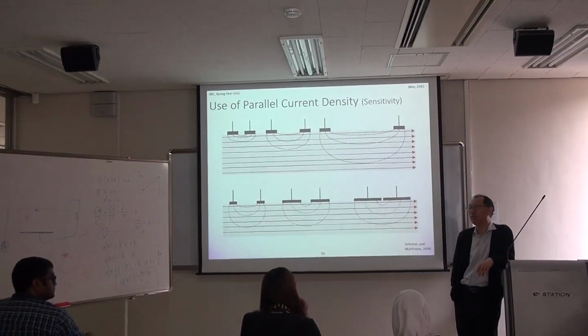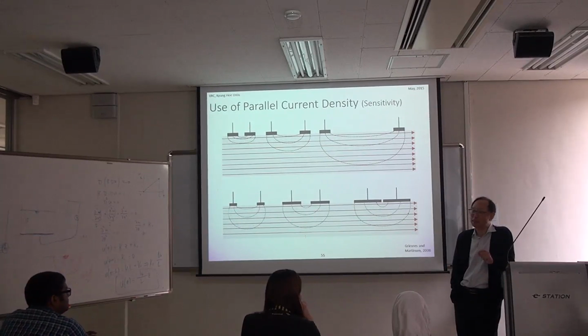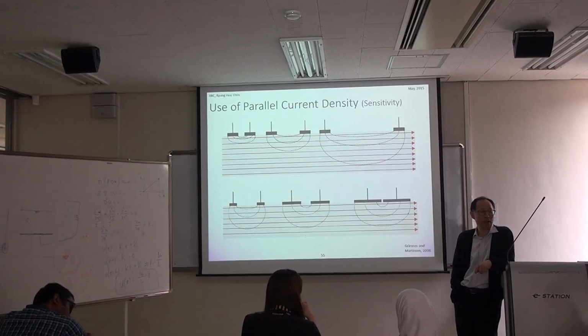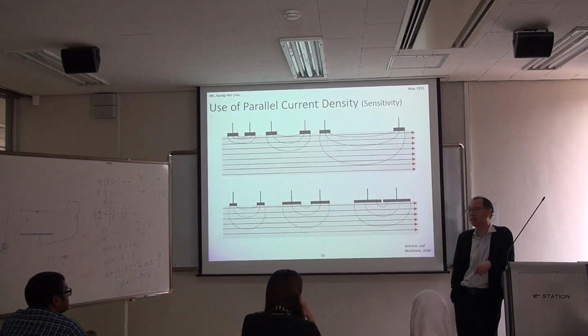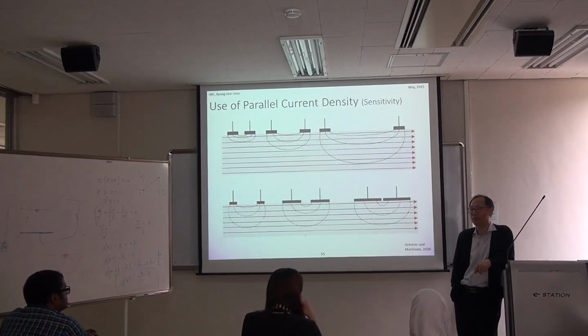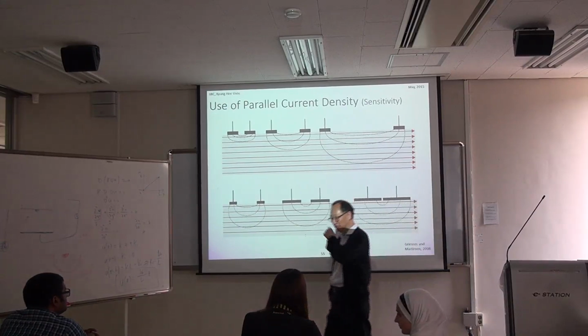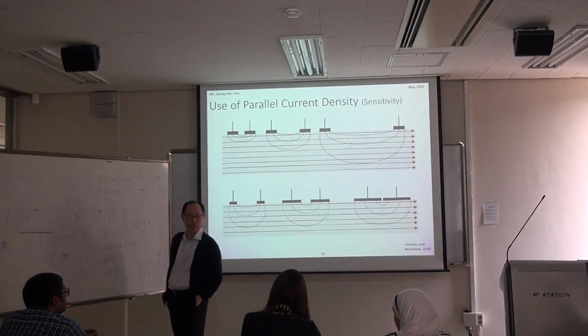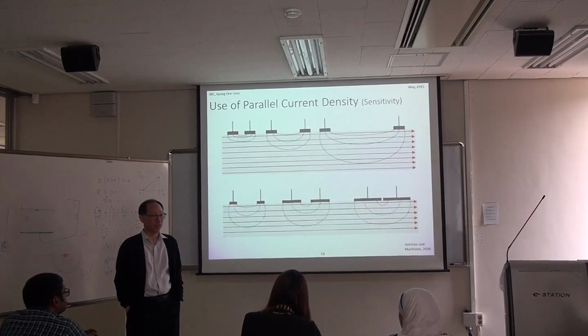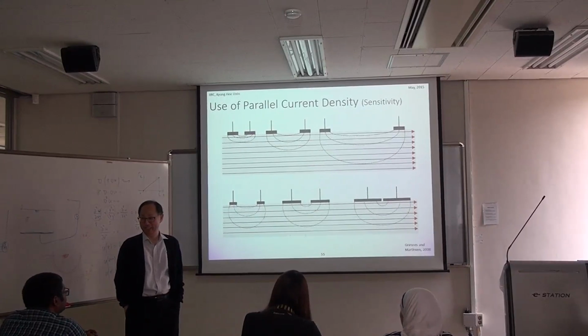Then you can come up with probably not the best, but a very good electrode configuration for your application, which will improve the performance of your signal, sometimes very significantly. So without knowing this kind of lead field concept, sometimes you come up with a design which is basically nonsense. Okay? And you don't know why. You don't know why you don't have signal.